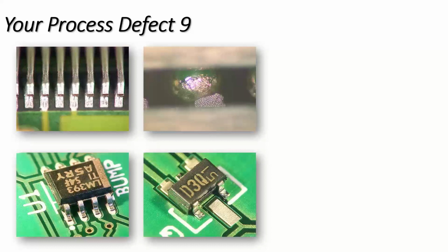Another experiment that I've done in the past is taking boards, printing paste, and using a glass slide. So putting a glass slide and changing the profile with a profile simulator. So basically a reflow oven with a glass window and a camera on, and seeing how the profile affects the amount of volatility.